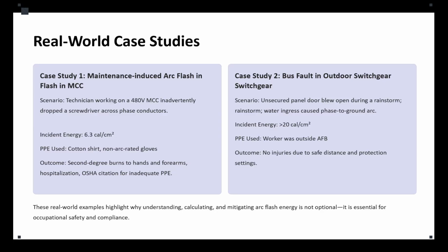Now, the MCC was energized and under normal operating load. We didn't have any lockout or tagout in our system. The technician was working bare-handed in the energized area, and the PPE included a standard cotton shirt and non-arc-rated gloves. Okay, the screwdriver was a standard metallic hand tool.